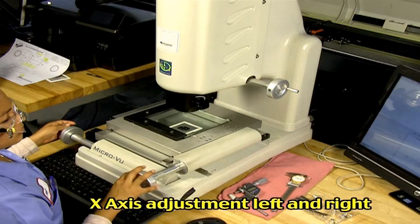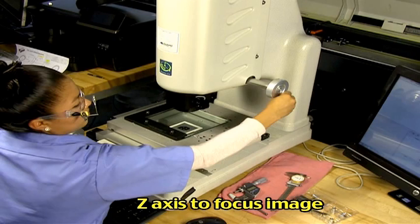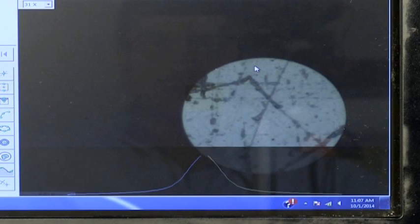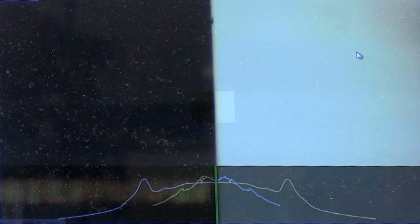The x-axis knob moves the table left and right. The y-axis knob moves the table back and forward. The z-axis knob is used to raise and lower the camera to focus the image of the feature being measured. During focusing, 2 vertical green lines appear on the screen. When the green lines overlap, the lines will appear as one and the object will be in focus.